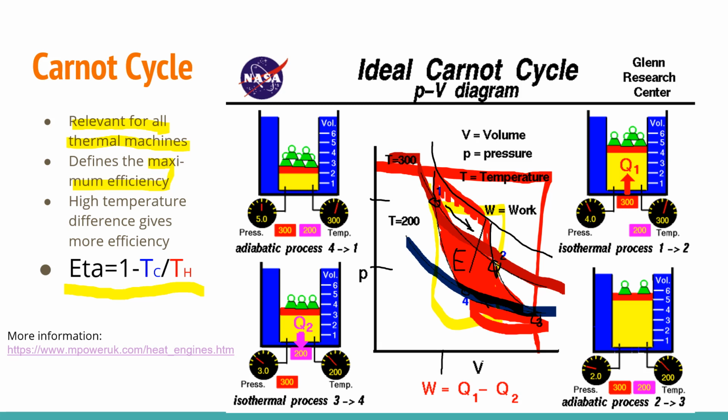And to have that, you should not subtract too much. So if you want to subtract a very small number, you start with a very low temperature. Then you divide that temperature by a very high temperature, and then you subtract a small amount here, and then you have high efficiency. So try to make this small. If that is small, then you have high efficiency. Now, when is this number small? The one way is to reduce the lower temperature.